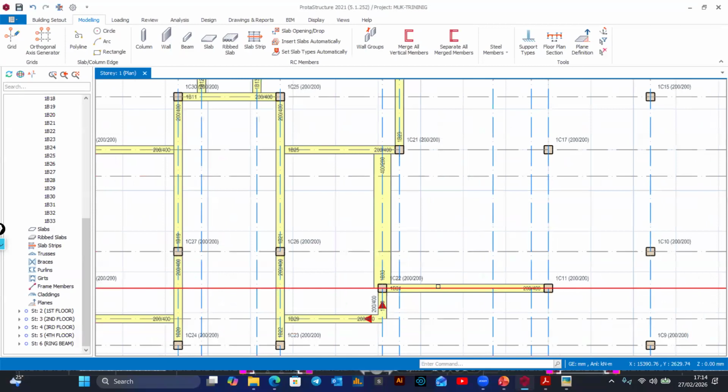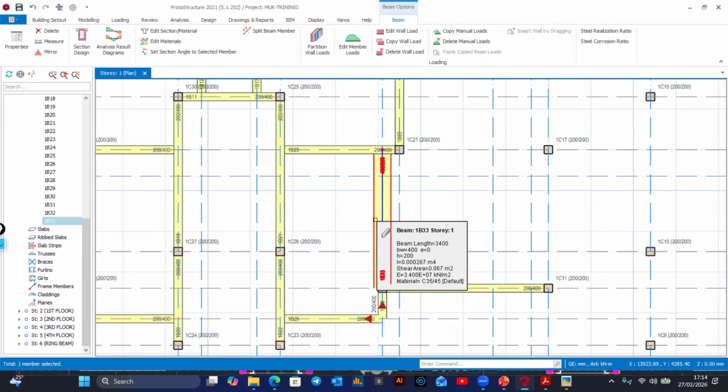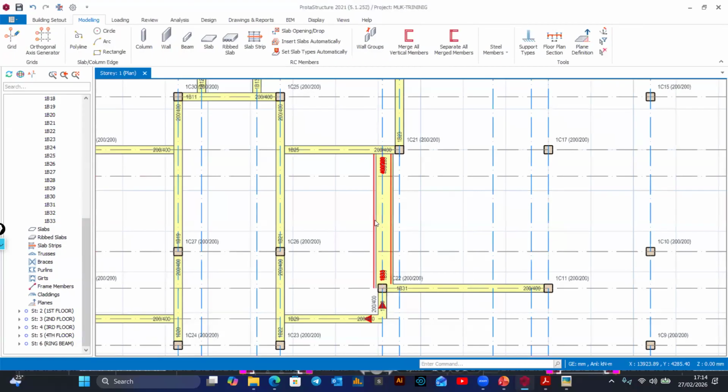So you should avoid making random movements when you are designing. This business of just clicking on the element and then pressing the arrow key on the keyboard to shift the position. You need to be accurate. You need to know the exact distance which you are moving. So you can right click and then get the measure tool.